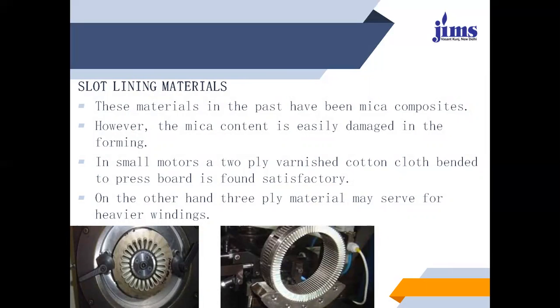So this is the structure of this type of material. This is plastic in nature, or a material related to mica, which is provided in between the slots, and then we provide the winding over this. This is the structure we find on the slide, and the coil will be inserted within the winding. It gives protection between the winding and the core of the stator or rotor structure.